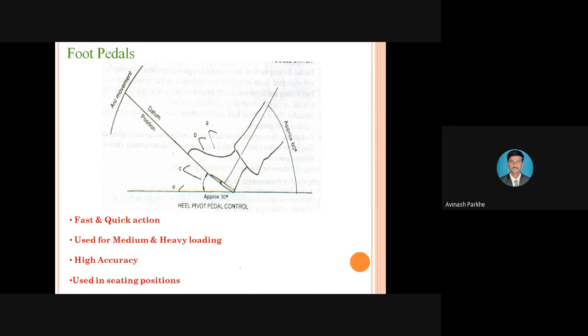Whatever number of pedals are available, they should be properly designed so that the driver can easily press the clutch pedal, easily press the accelerator, and easily press the brake if I have to reduce the speed of the vehicle. While designing the different types of pedals, ergonomic factors are to be considered. Here you can see the figure: the pedal will be in an inclined position, and the leg of the operator is also there.